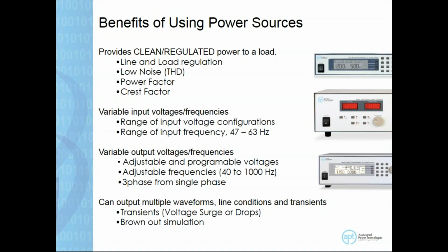Now, the majority of current generation power supplies are able to display the power factor of the load. Why is this important? Power factor of the load allows you to record how much power is being used and how much power is being delivered to the product, and also how efficient it is. So a power factor of 1 will indicate a really efficient product. A power factor of 0.7 may indicate that 30% of the energy is wasted.